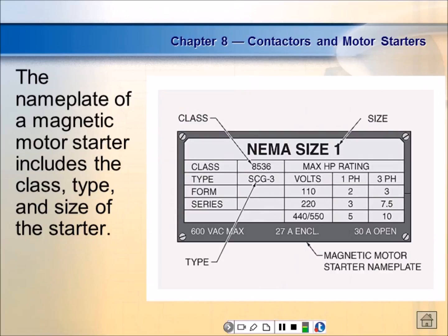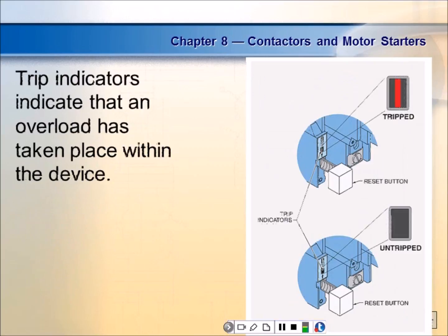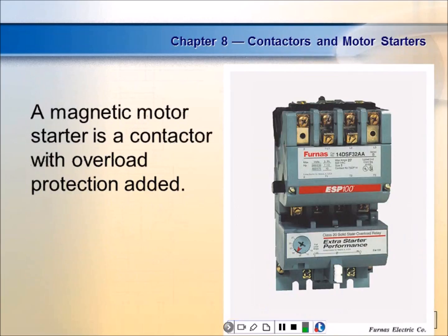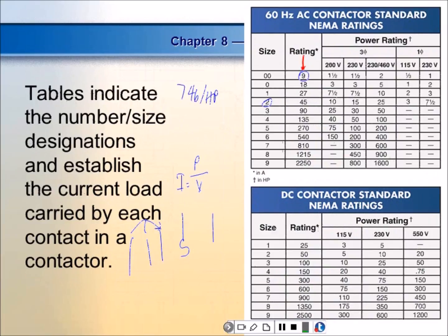This is the nameplate on the motor starter. So this figure doesn't give us very much information at all. All it says is NEMA size 00, and then it says the contacts are rated at 9 amps. But we already know that, right? And the problem with these nameplates, of course, is over time, sometimes they fall off. So this is good to keep the book for. And also, this information is also in the NEC code book inside their motor section. So if you got a code book,